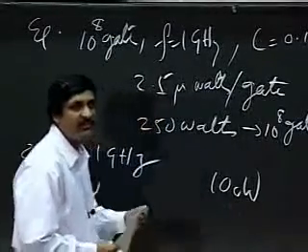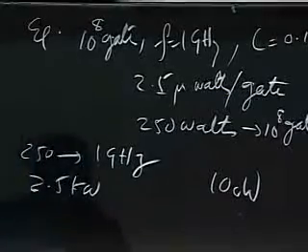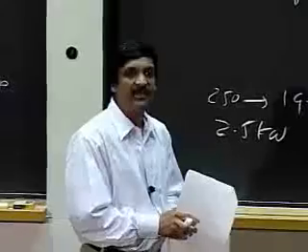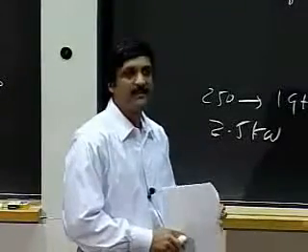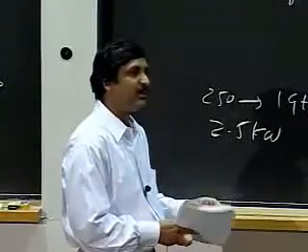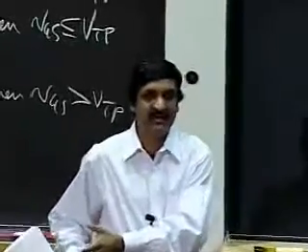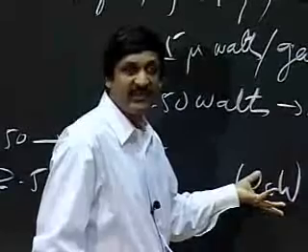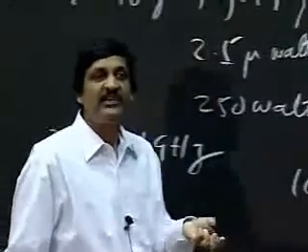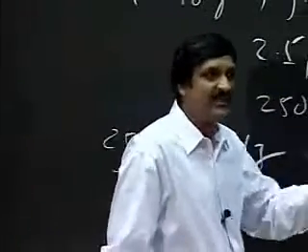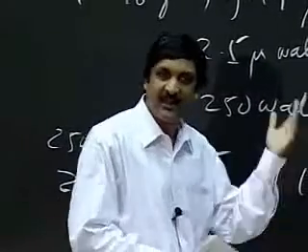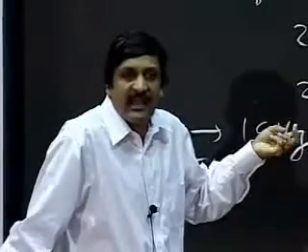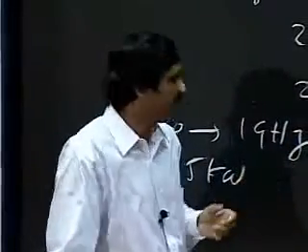One trick is to play games with the clock. Let's say that in some computation you are not going to be using your floating point unit, or your integer adder unit. You can turn off the clock to those devices so that they do not even switch when they're not working. If you turn off the clock to a device, it's just going to sit there in limbo without consuming any power.